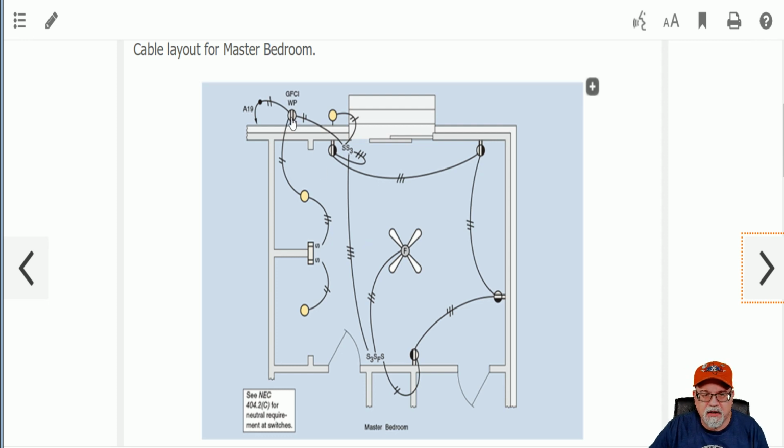Now, in this case right here, you see where once it came from here, this is why it ends up putting 6 conductors in here, right? You have a 14-2 here, 14-2 here, 14-2 here. Of course, you've got an equipment ground. All count as 1 when you're doing that box fill, and the device is 2, double volume. So you have to think about that when you're doing this box, okay? Box fill. Hopefully you've watched our videos on box fill. Very important. Don't take it for granted. Just because a cable can make it in that box doesn't mean you can use that box, okay? Got to think about those things.